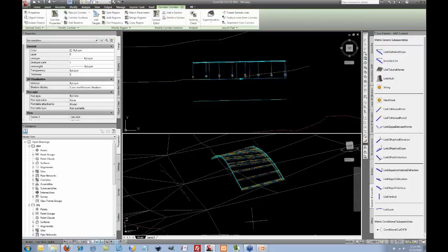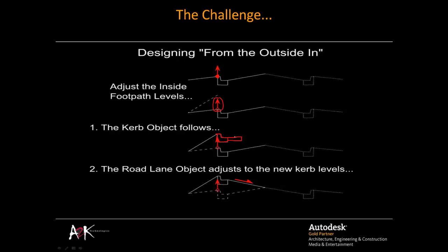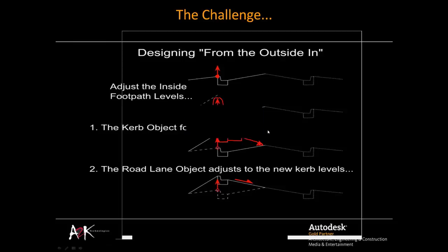Now what this means is, if we go back to the PowerPoint, let me just clear this drawing I was doing. So what we've done here is we've switched the focus onto this string here that I'm just drawing on. We have used the profile to raise that, as we're showing here, and the curb and gutter has come with it. The lane was attached to that, but the width was just like 2 meters, it was random. So we've now stretched that back onto the center line. So it's a bit weird when you first see it, but it actually works very well.